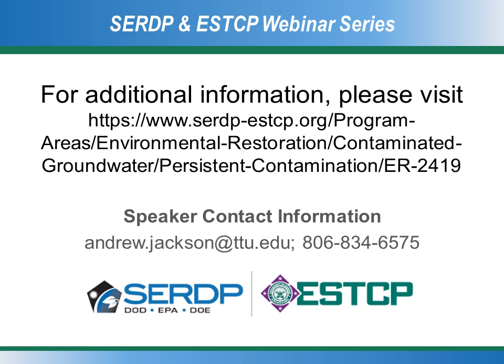It's also restricted to zones that you can get through reasonably well. If you have to hard hammer for very long periods, the membrane is not indestructible, and that can be a problem. We also have not evaluated the maximum depth we can go to. We've gone to 30 feet, but we have not tried to push to greater depths. There's really no reason why it can't go deeper, as long as, like I said, the membrane's integrity is able to withstand the amount of force and the vibrations required to get through it.